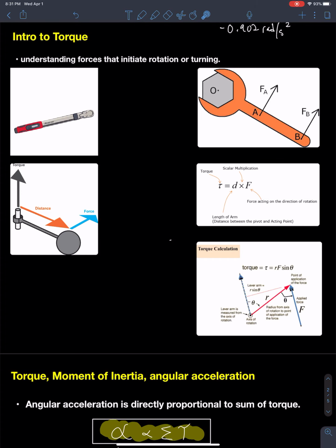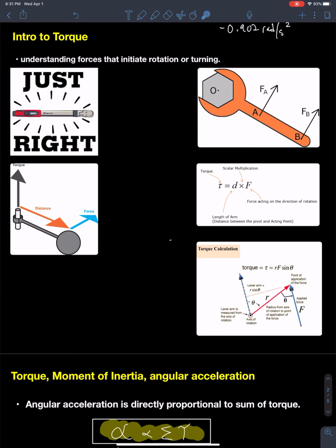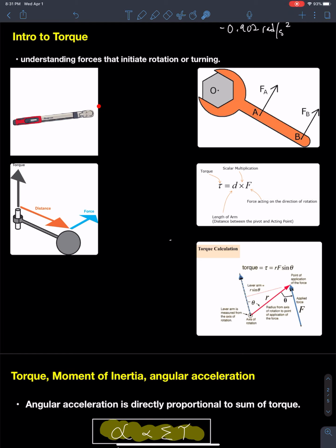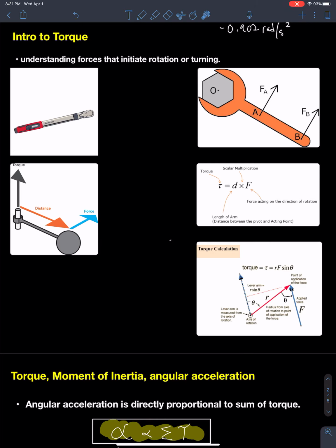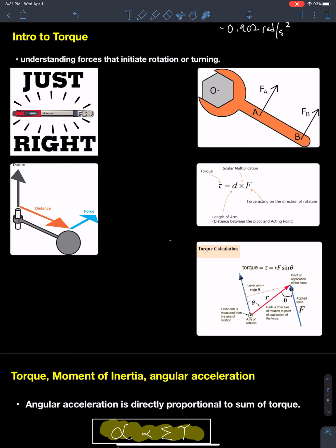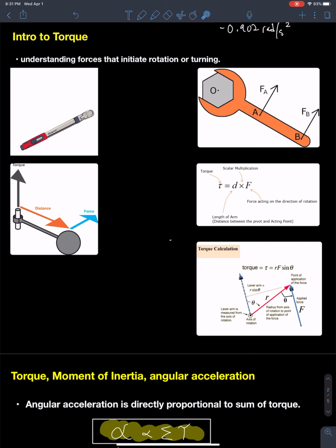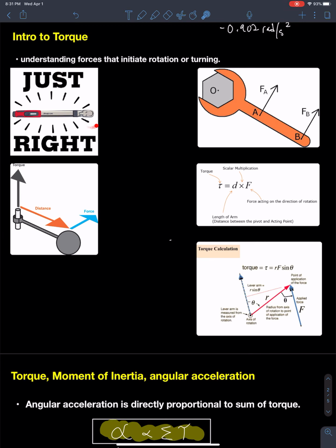So if we're dealing with delicate systems, like for example, engines in a car, all the bolts in your car have a suggested amount of torque to put onto them. If you don't put enough, the engine is going to vibrate. If you put too much, you might seize that part and it'll be impossible for you to take it off. It might put too much stress on the system. So mechanical engineers often work with torque, okay?